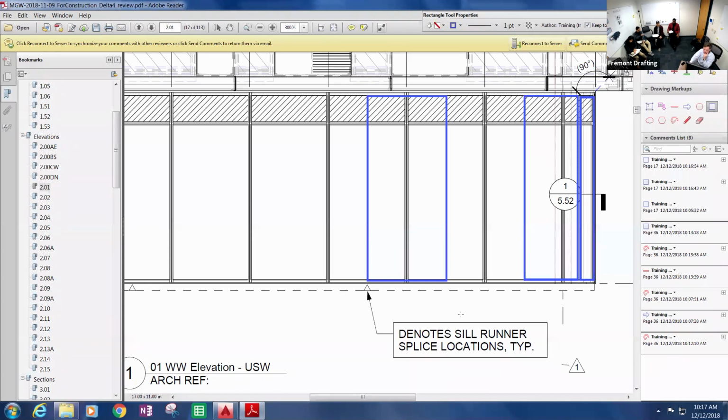But now when we look at anchors, the tributary area changes. When I'm looking at the anchors of this vertical mullion, there's wind load and dead load on that anchor, right? For the dead load of this anchor, the tributary area is the same as that, because I've got a setting chair here picking up half of this light of glass, and a setting chair here picking up half that light of glass.